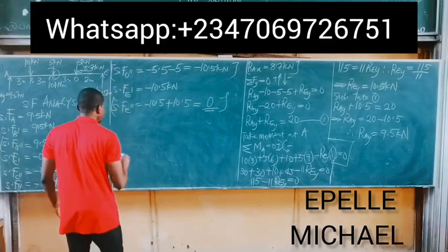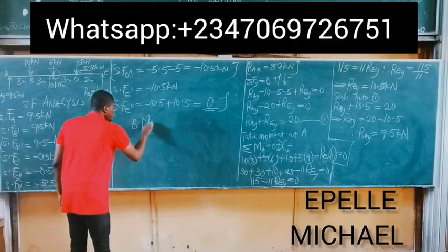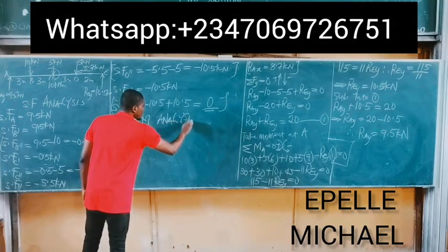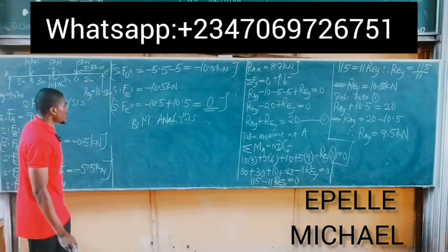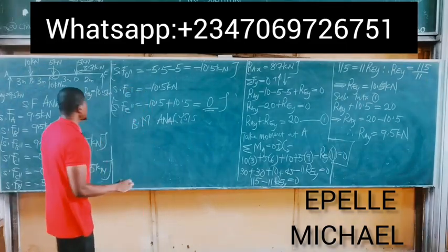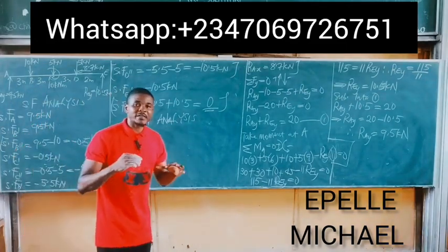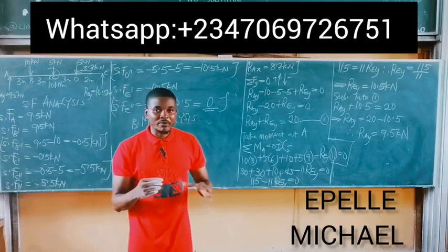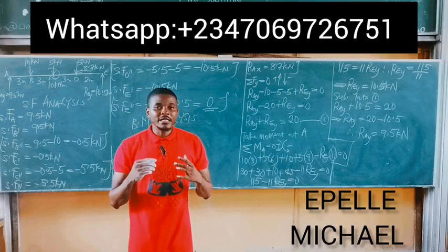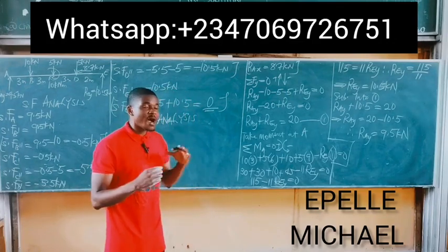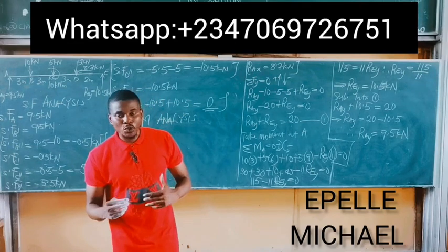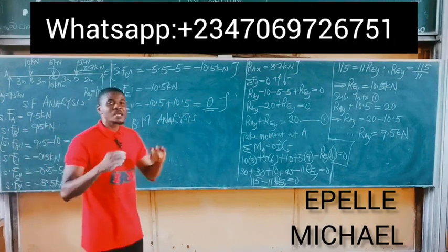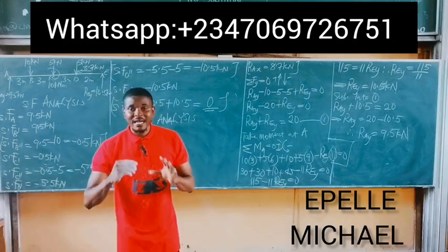Next is to start the bending moment analysis. Okay, so bending moment is simply the summation of the entire moment acting on the beam from the beginning of the beam, at each point of the beam, to the end of the beam. Now in bending moment, we also consider upward force to have positive moment, while downward force should have negative moment. So let's continue now. For the equilibrium law, the moment of every force at every point is automatically 0.